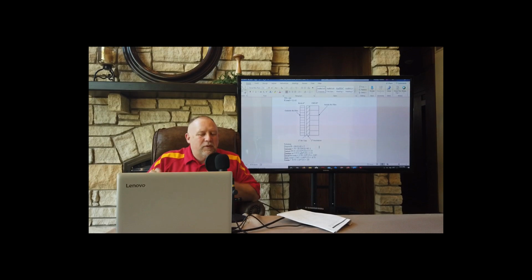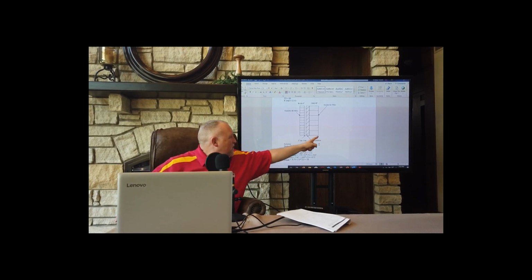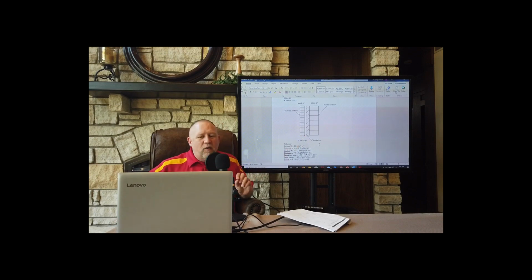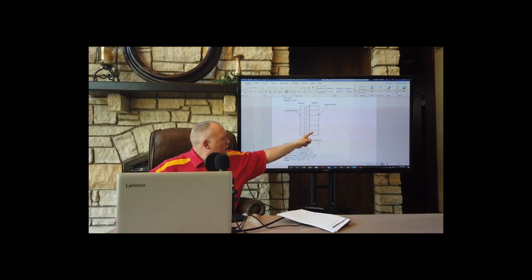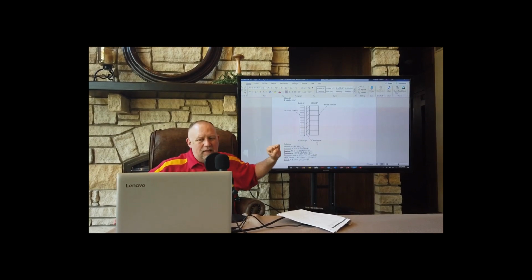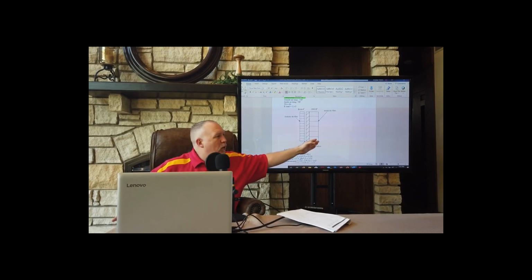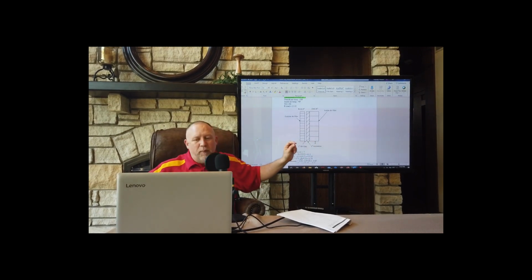So being able to do this math, also something else important, notice these temperatures. It's 65 degrees there, it's 57 degrees here, and then it's 1 degree over here. In other words, in this wall, this block is never subjected to freezing, at least at minus 10 degrees, right? In other words, we have moved the point of condensation outward, and we've moved the point of freezing outward.